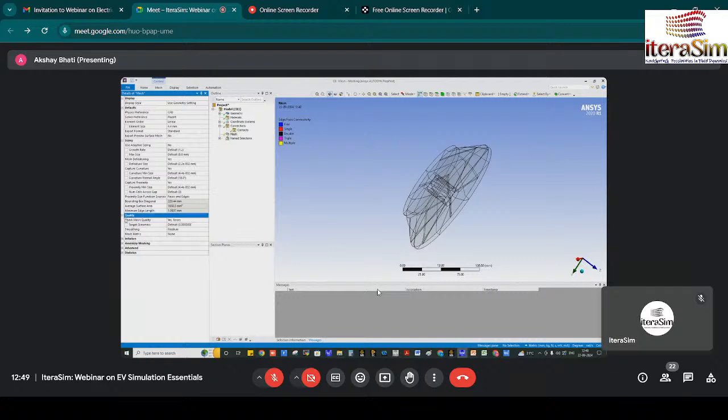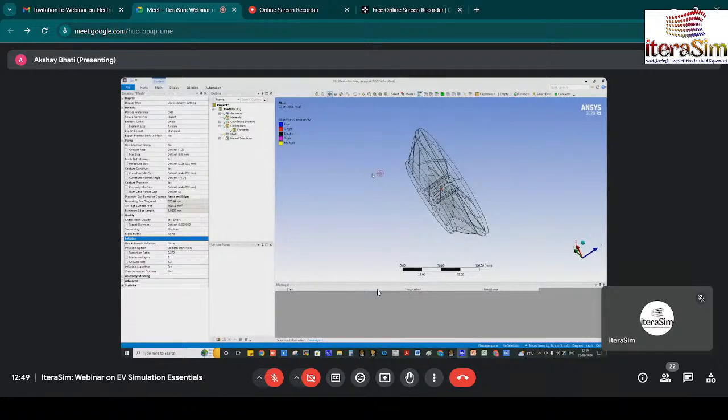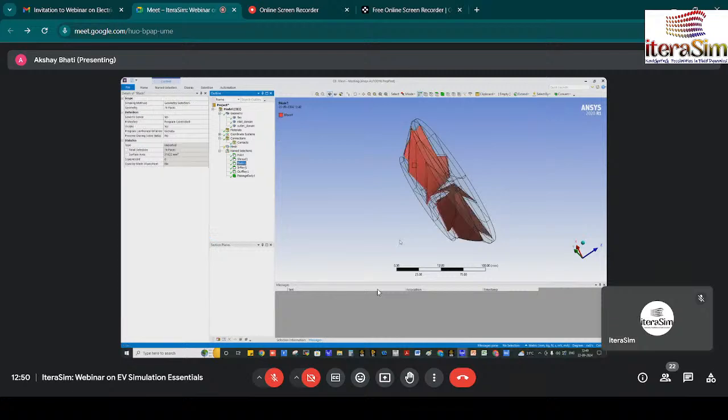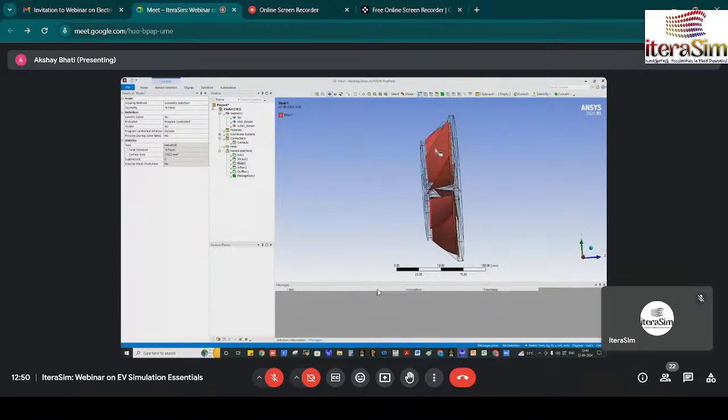And in that fan system, if the fan speed is very high, we need to provide an inflation region to capture the boundary layer near the blades. If we talk about the blade, here is that blade. If you want to simulate that fan accurately, you have to give an inflation layer to capture the boundary layer near the trailing edge and near the solid portion, the wall of the blade.